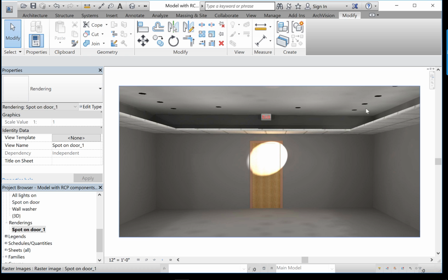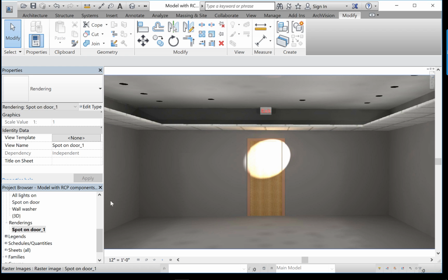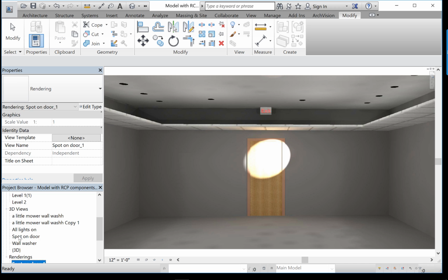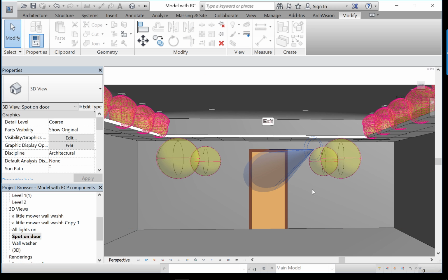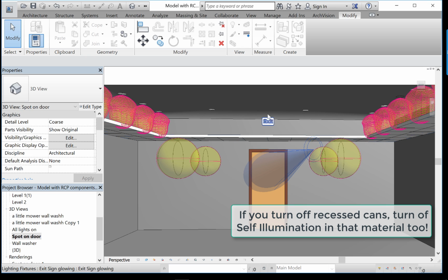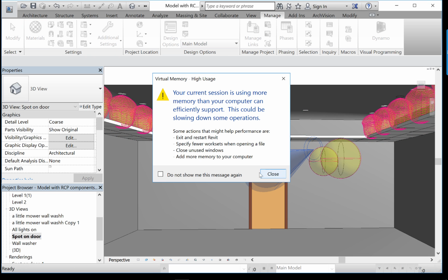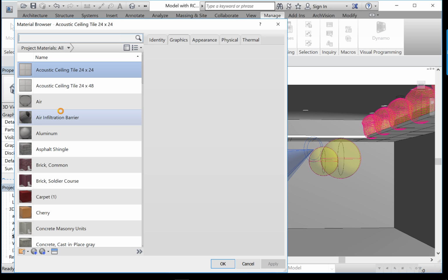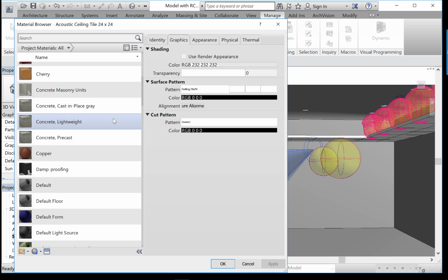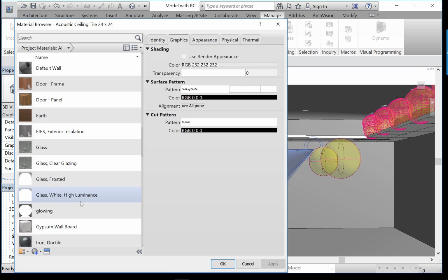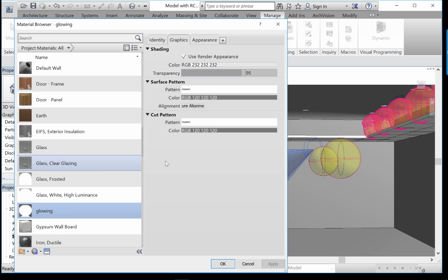And you see how in this view I've turned off everything except basically a spotlight and those hanging studio lights. Let me go over here and show you this view. I've turned all those off. You have to remember that if you're planning to render that view, go beforehand, go to your materials library, and take a look at that rendered glowing material, wherever that is. I forget which one, maybe the one called glowing.